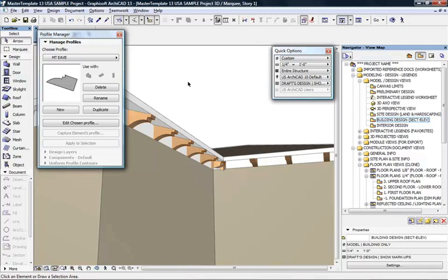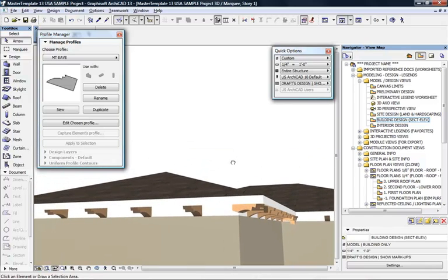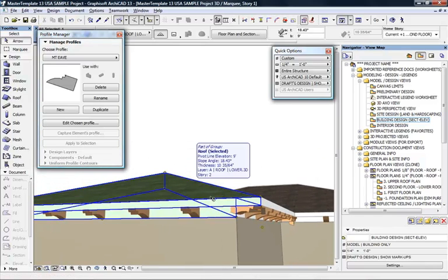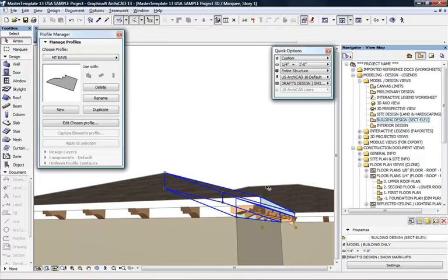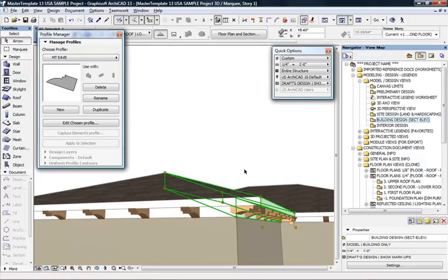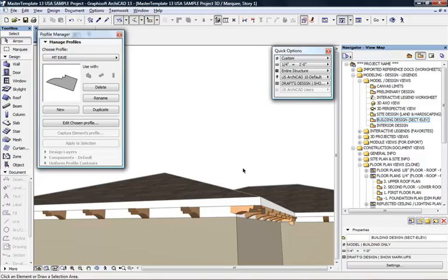A great way to use solid element operations and complex profiles to create rafter tails with a sculptural form, and how to also prepare the roof with a solid volume in the main area, but a shape here you can see notched out to allow the rafter tails.